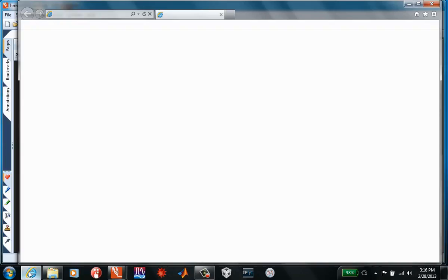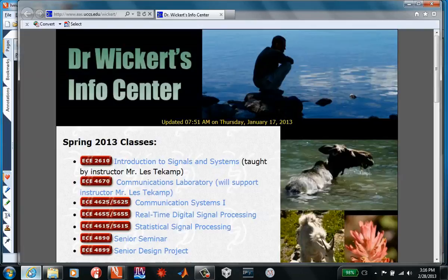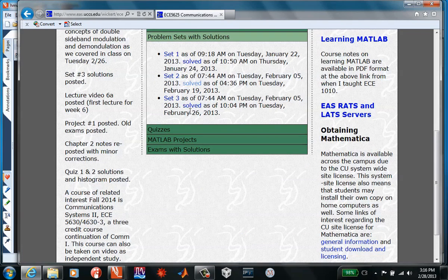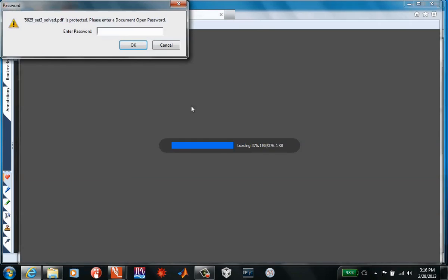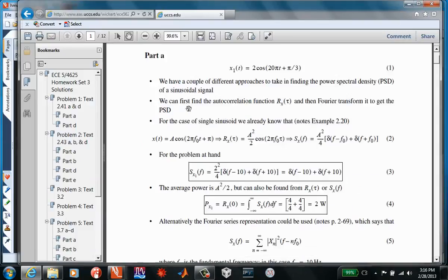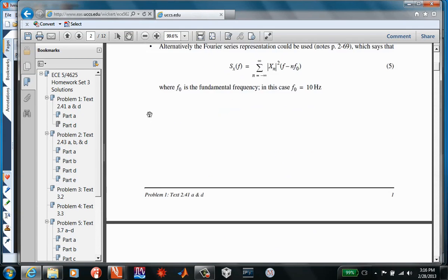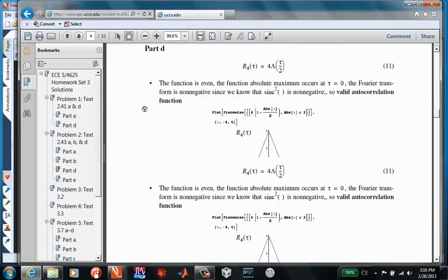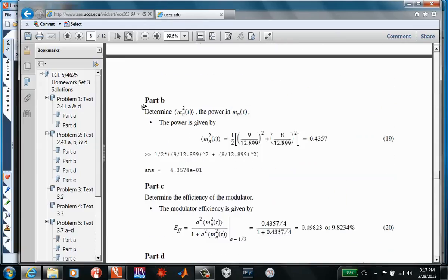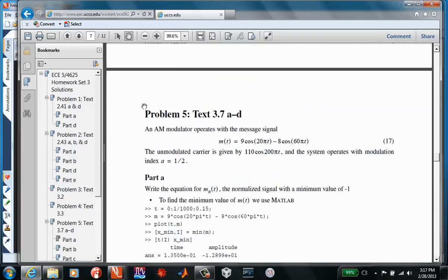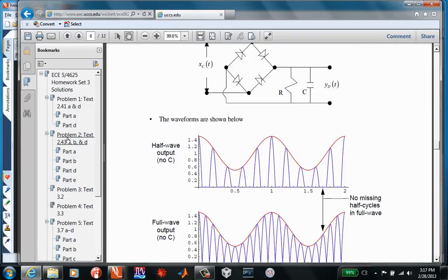We're waiting. Are there any other questions pending now in the queue? Is DSB like a larger set that includes AM demodulation? It seems like you're using the same process. You're multiplying by a cosine and you're filtering out the higher frequency stuff, and you still have the upper and the lower sidebands in AM modulation. So is AM one kind of DSB? It's probably DSB? Yeah. Keep going.